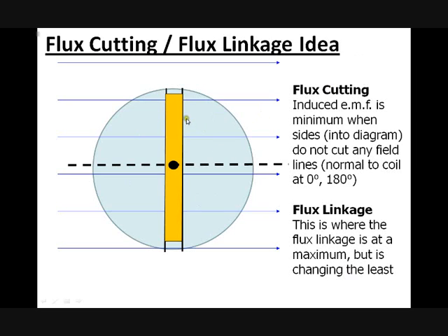Flux cutting, it's not cutting any, EMF is a minimum. Flux linkage, it's at its maximum, but it's not changing. So EMF is the rate of change of flux linkage, so minimum EMF.